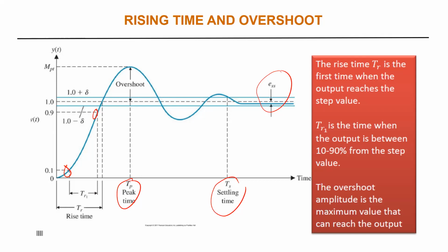The settling time is defined as the time needed for the response to go within, let's say, a certain percentage of the final value. Ideally, you would like to go to 1, but that might take a long time. So you have to be practical. So you take a certain range, which is, let's say, I will tolerate my response reaching within 2% of the final value, that will be fine with me. In certain applications, maybe within 5% of my final value. Okay? Any question here?